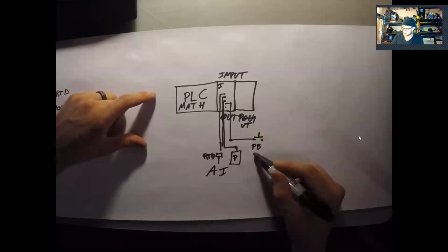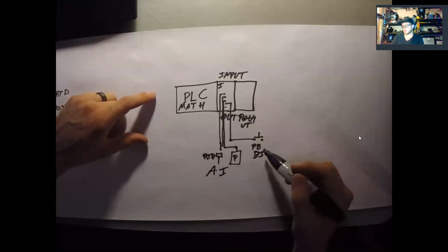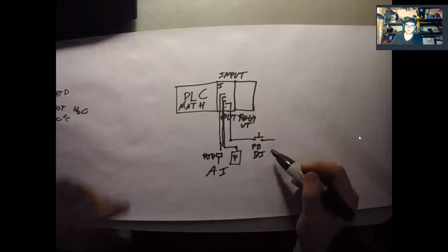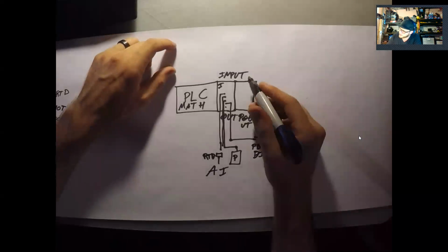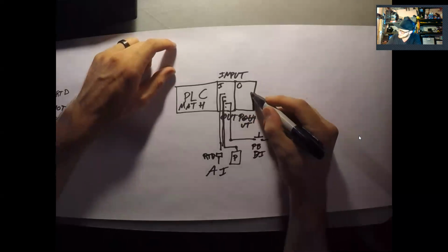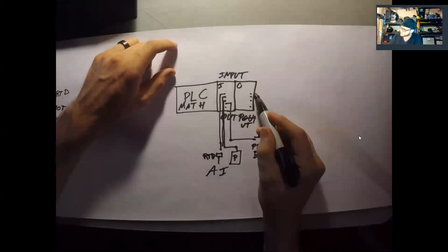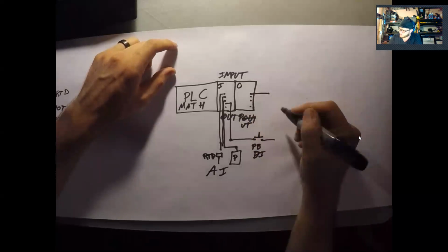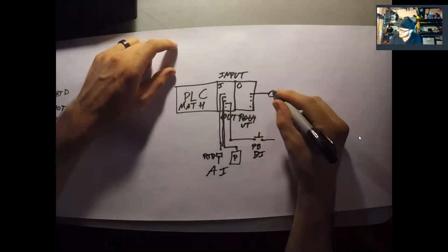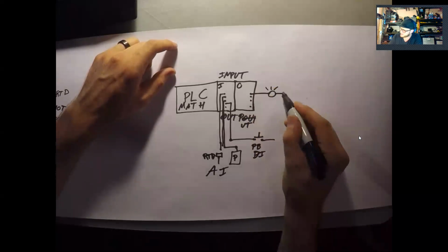Right, and that's a discrete input. So a push button would be a discrete input, right? It's open or closed, okay? And then over here in your outputs, your O module, you're going to wire to things like lights, right? We talked about that earlier.